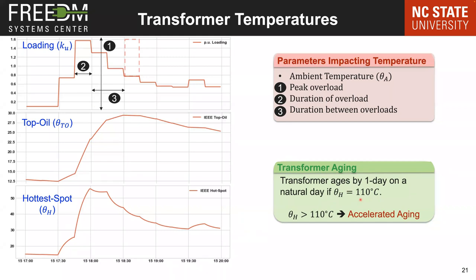And that's dependent upon the oil type, perhaps, in the transformer? Yeah, so generally right now, there is a rating for the oil that says 65 degrees Celsius rise above ambient. So either it's 65 degrees Celsius rated or 55 degrees Celsius rated. I think after 1970, all of the transformers installed were 65 degree rated rise in temperature. So for all those transformers, this is the actual aging limit for the transformer. Okay, that was a question from the chat. Thank you.